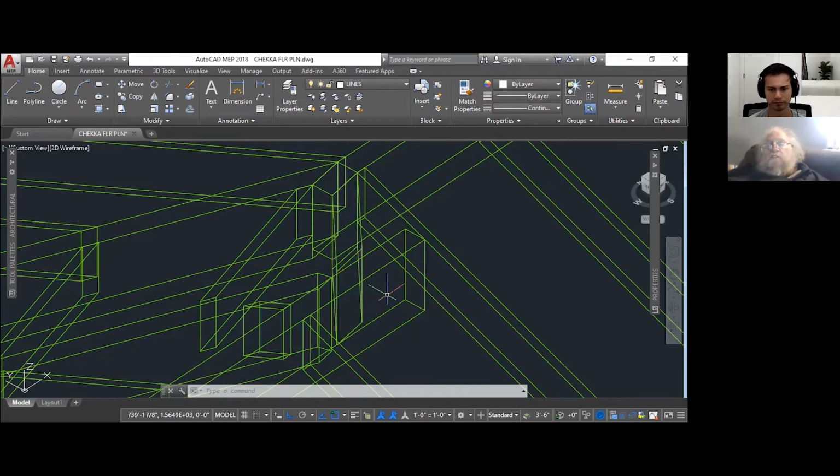But for convenience's sake, and because we can just make it out of a scrap that happens to be laying around, and because it's going to oppose this full-length hip on the other side of the ridge, and perhaps the engineer has a connection drawn, maybe he has a detail here that shows this hip cut like this. Probably he's got this hip bolted to that hip through the ridge.